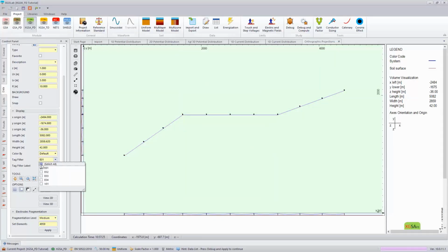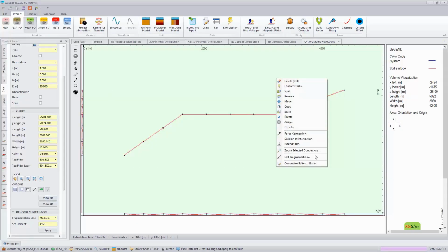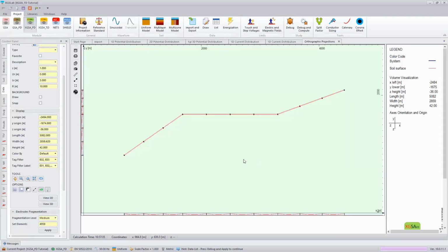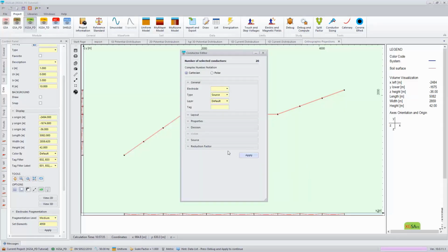Next, we're going to take a look at our other phase conductors, and we'll just zero these values out. This isn't necessary, and actually in a normal faulted condition these phases will have normal load conditions. However, we do want to match the tutorial documentation. So we're going to modify the source current on each of these other phases to be 0.